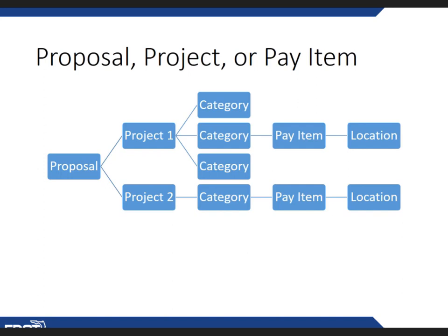Yes, LRE under roadway. And the basis of estimates addresses if you have a pull box for lighting, but you don't have lighting component plans because you only have one pole you're installing. The FDM or PPM already address how to include the appropriate lighting sheets in your roadway plans, but they still address lighting. They still need to be accounted for correctly, and you can review the BOE for ensuring that they are on the correct tabulation sheet.